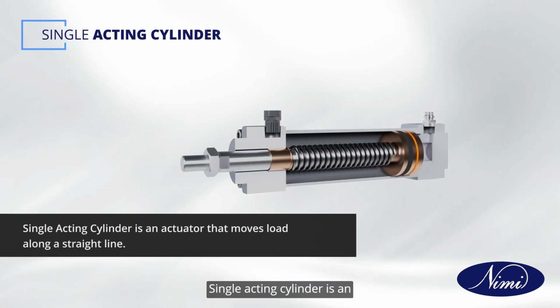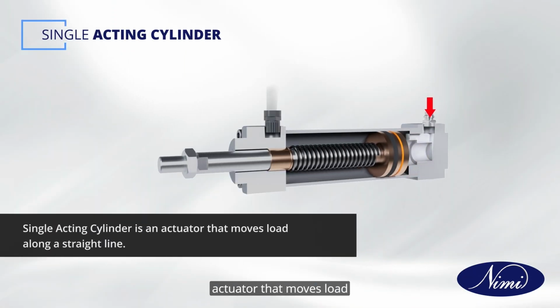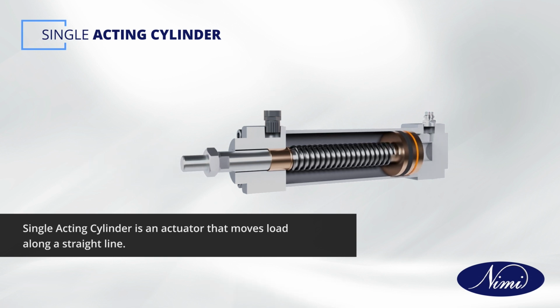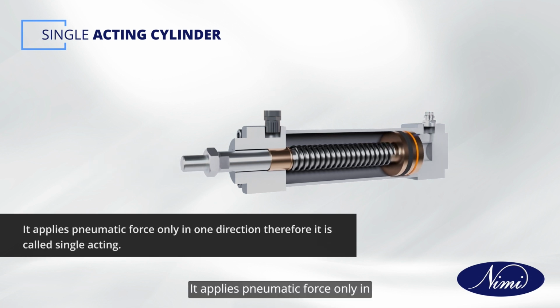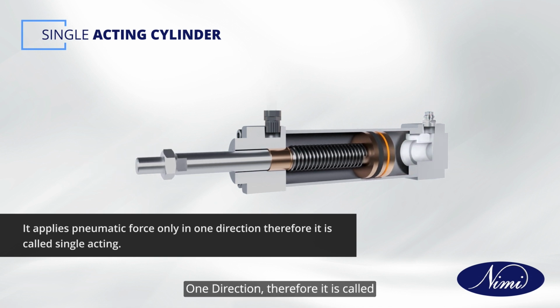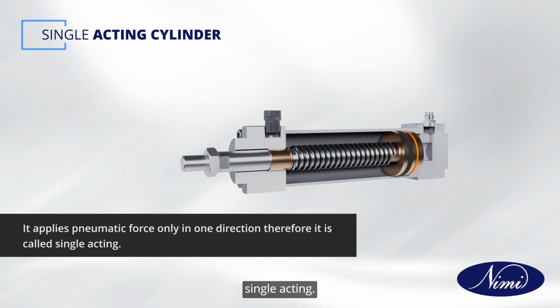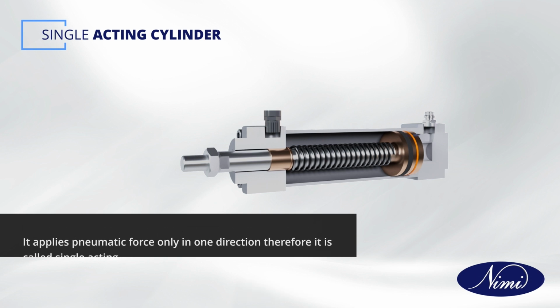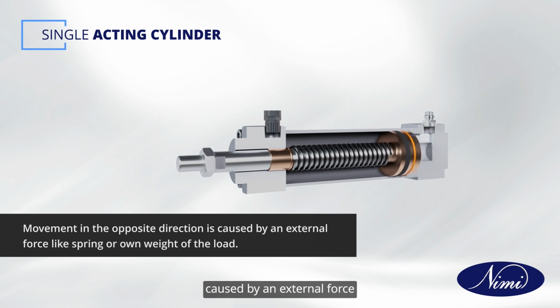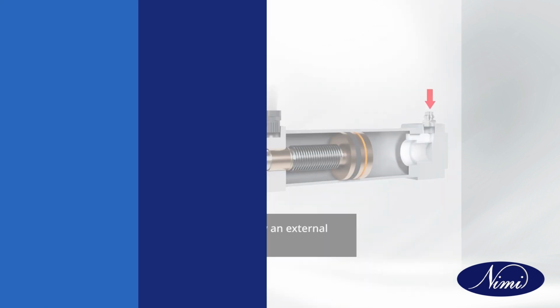Single acting cylinder is an actuator that moves load along a straight line. It applies pneumatic force only in one direction, therefore it is called single acting. Movement in the opposite direction is caused by an external force like spring or own weight of the load.